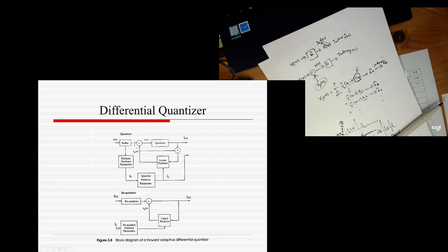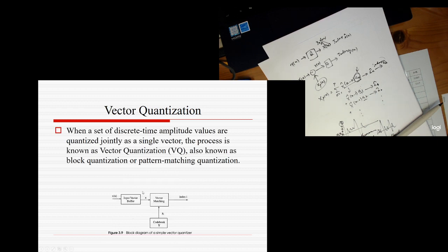So they get the index, and dequantize to get A1 hat, A2 hat, up to AP hat. So they know how to do the prediction and predict the current data, and sum it back. So you have an additional overhead to inform the decoder how to do the linear prediction. This one we call forward adaptive.